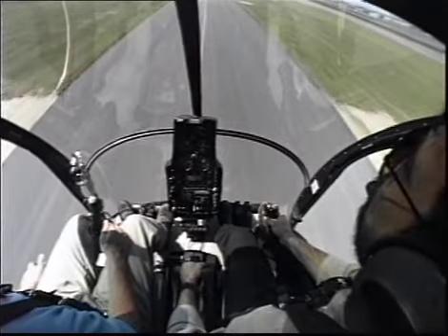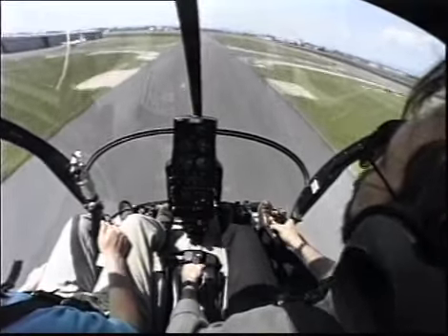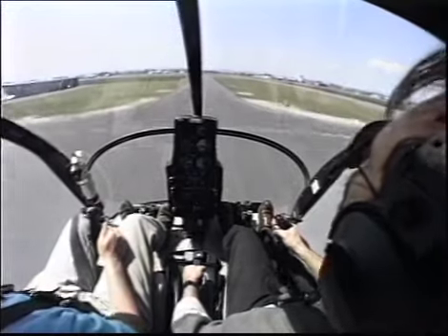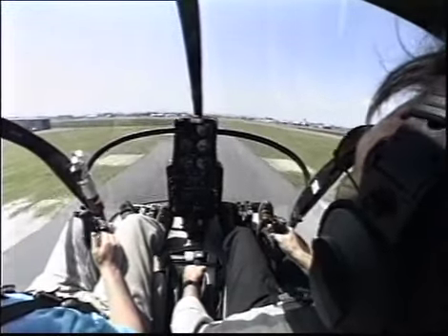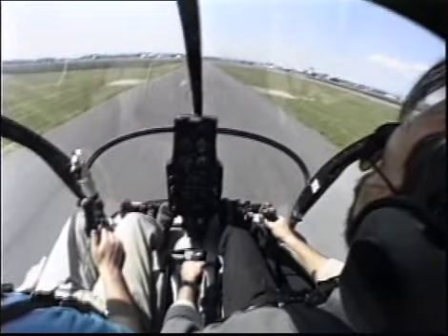You know, there probably isn't a helicopter maneuver that's more impressive than the quick stop. You'll practice the quick stop or rapid deceleration for a variety of reasons. One, it's an excellent coordination exercise. A good quick stop requires a high degree of coordination of all the flight controls, cyclic, collective, throttle, and anti-torque pedals, in a constantly changing flight situation.